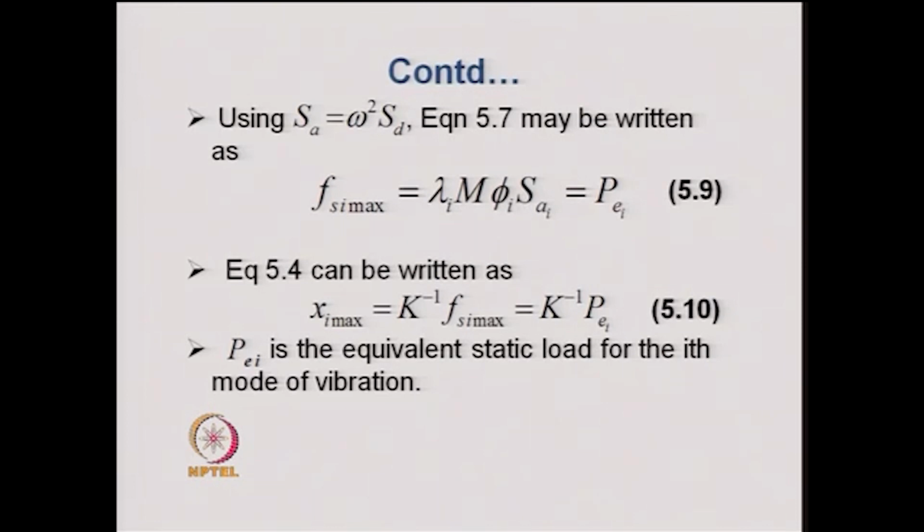Therefore, this load PEI is an equivalent static load, and if this equivalent static load is applied onto the structure statically, it will produce a displacement in the structure which will be equal to the maximum displacement that the structure would have if it were vibrating only in the ith mode.